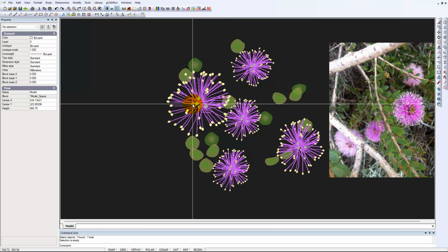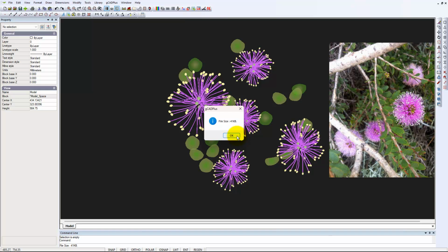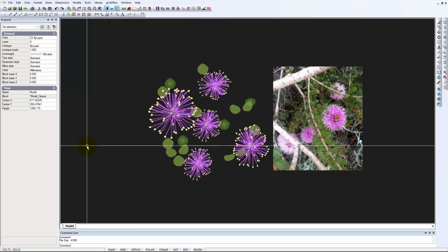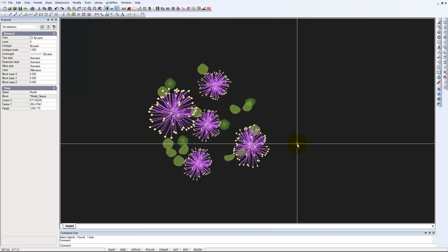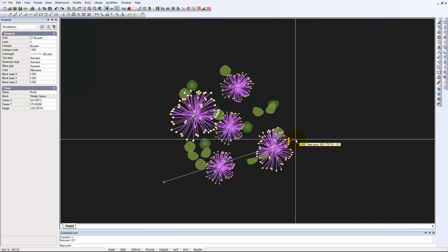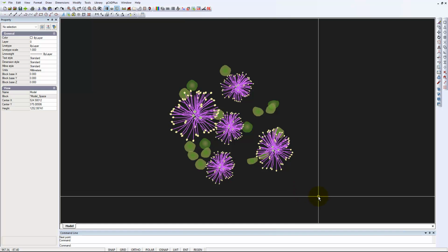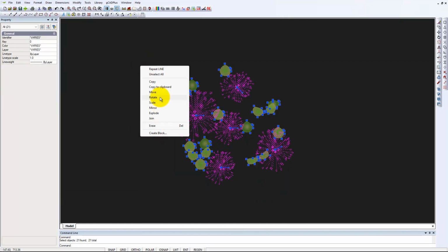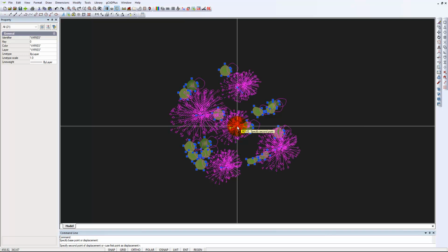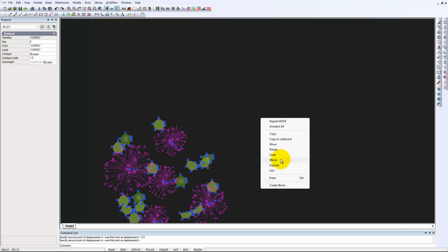But I've now duplicated all of those, and let's have a look at the file size, and we're still at 41 kilobytes. So I would argue now that we could get rid of the image, we could zoom extents. Just always make sure that at this stage, if you start a line at 0,0, see how 0,0 is down here. Well, what I'd now do is grab all of these and move them from the centre there to 0,0 and zoom extents.